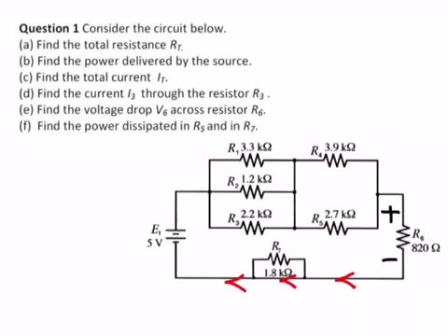The second thing to notice, we have a current that will be drawn from the source, from the battery. This current here is called I total. This current will see three branches, then it will split into three currents. So I total is the sum of these three currents. And then this same current will flow in R4 and R5. So the current I total is the same current flowing in these three, the same current flowing in these two, is the same current flowing in the resistance R6.